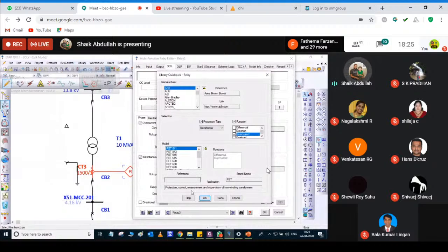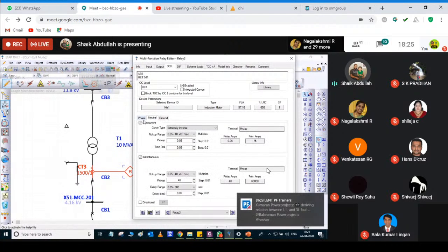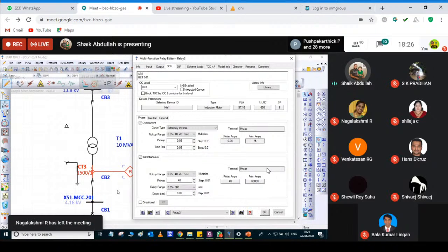And this is RET protection. I'm going to use the same relay, and I'm not using any ground fault. I'm using only neutral. Any phase CTs I'm using, because I'm not configuring any ground CT here, like what I did in the motor. Here I'm using only the neutral. For that I'm going to give the settings, and I will give the coordination between the downstream relay and the upstream relay. Then I can wind up the class session, I think.